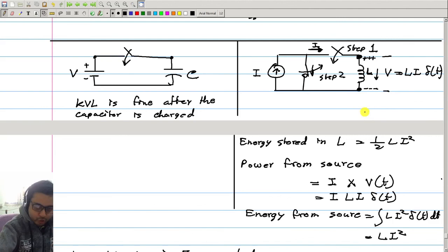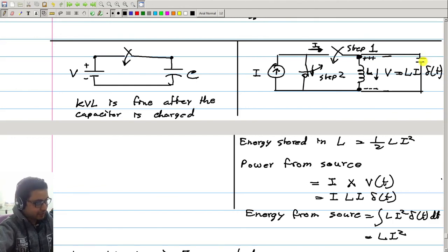Now one thing we can do, this is within our capabilities: model this thing as a parallel capacitance. Because you see we are getting an accumulation of charge, because we are having more current here and less is passing, and that accumulation of charge can be modeled using a capacitor. Now maybe that capacitance is very small, very negligible, so that's why we are ignoring it, but definitely there is some capacitance.